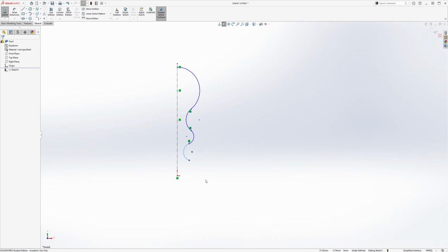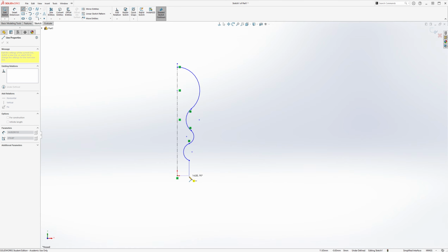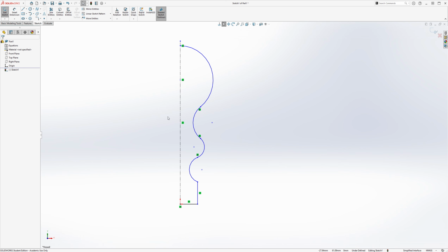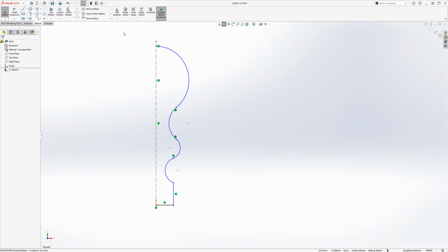And then I'll just close it off with a base like this. Oh, where's my line? Like this. But of course we actually have to add those constraints because that's just the auto detection tool. It doesn't actually constrain it for you, just lines up the geometry. So we'll have to do that ourselves. So let's make those 2 points vertical, and then this corner point with this arc intersection point vertical.